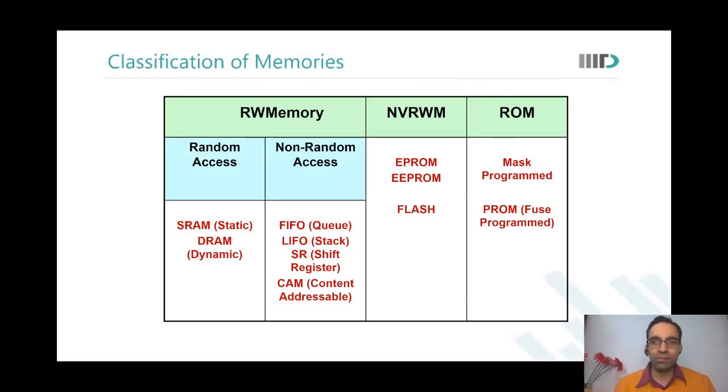Because if I'm sending 1 gigabyte of data from one part of the chip, and the other part of the chip can accept only 800 megabytes of data, then 200 megabytes of data we end up losing. We understand that not every cycle would require data transfer, and therefore we can still operate two different parts of the chip at different frequencies.